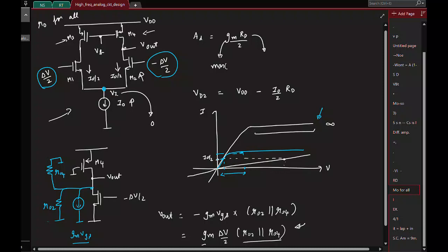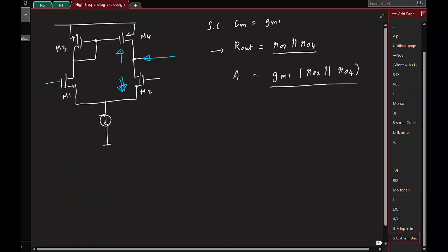Currents were flowing in both the branches, but we kind of discarded one of the branches. But here what we are doing is, currents are flowing in both branches, but although the output is taken from one branch, the current flowing in this branch is mirrored back here. So that way we are reusing the currents and not wasting them, and that's why the gain is kind of double. Okay, so this is another way in which you can actually derive the same circuit.